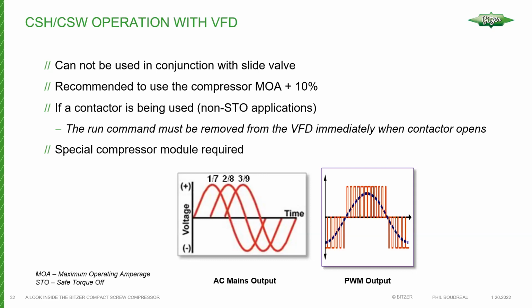Other drives you would use, you need to use the contactor. And then you just put the most critical safeties in series with that contactor coil. And then when that trips, your run command would be basically interlocked with that. So it stops calling immediately.